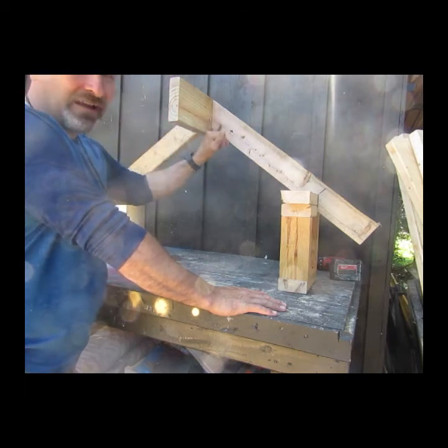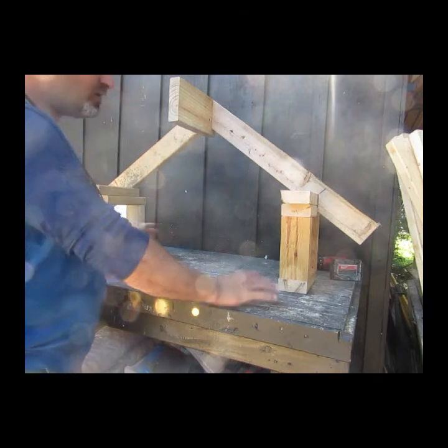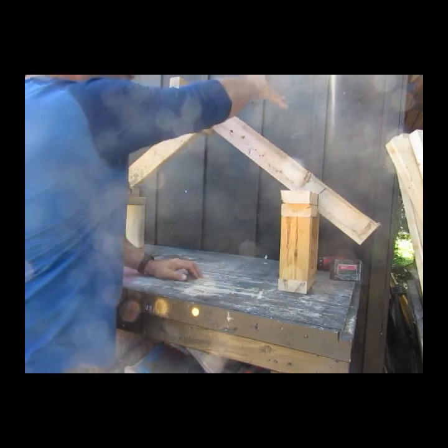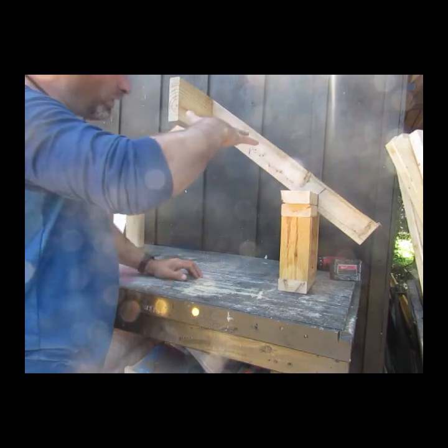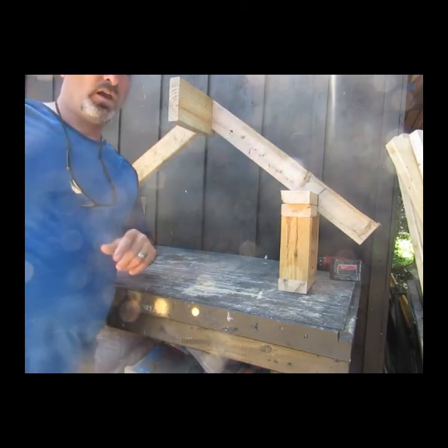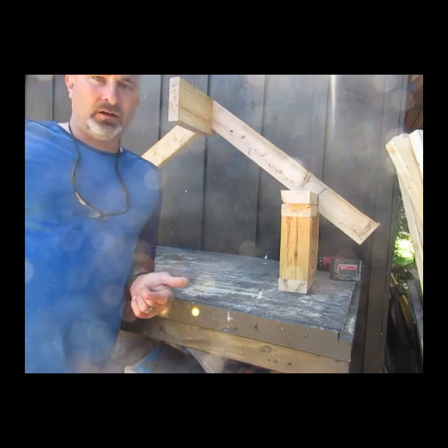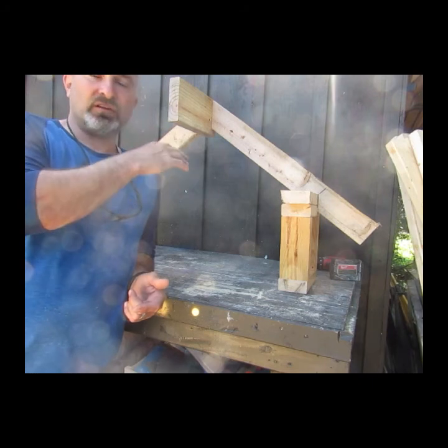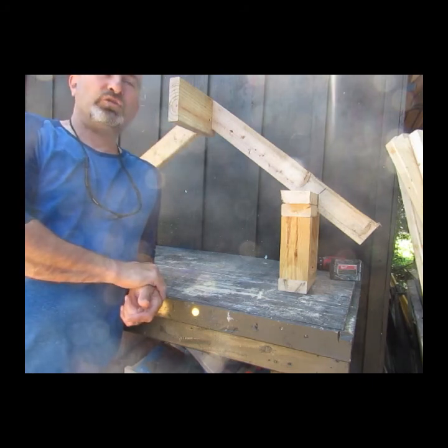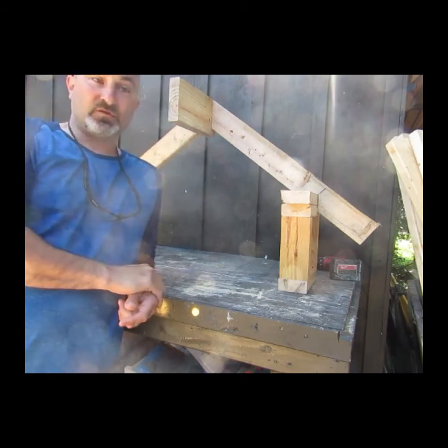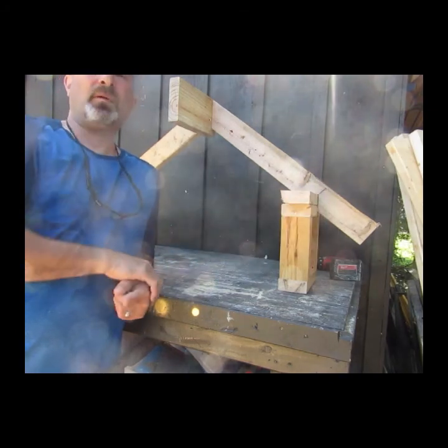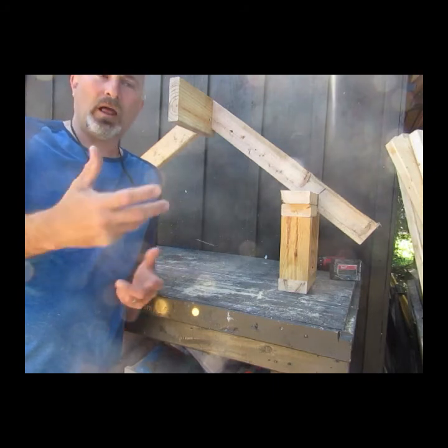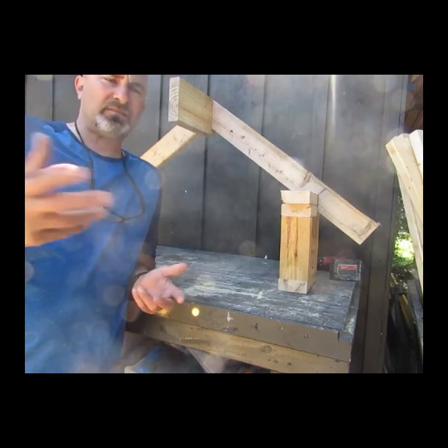These 2x4s can't span too far. If these walls were really far apart, you may have to bump these up to 2x6s, because the weight on this roof for a rafter would press down, and this 2x4 will only resist the bending pressure of a live load of snow and the dead load of the roofing shingles and the plywood to only such a distance. So once you go past a certain span, you've got to bump up the size. And again, refer to the building manual, the building code, and it will tell you how big a piece of lumber you need to span that far.